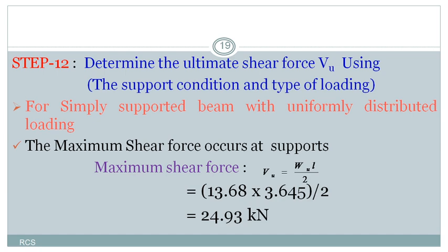Whether the slab is safe against the shear or not, that we have to check. Generally, slabs are safe against shear as well as in development length. Anyhow, we check whether, for the given data, they are safe or not. So as we are designing a simply supported slab with uniformly distributed load, we are assuming a 1 meter width of the beam and designing, so I can call it a simply supported beam with uniformly distributed load.